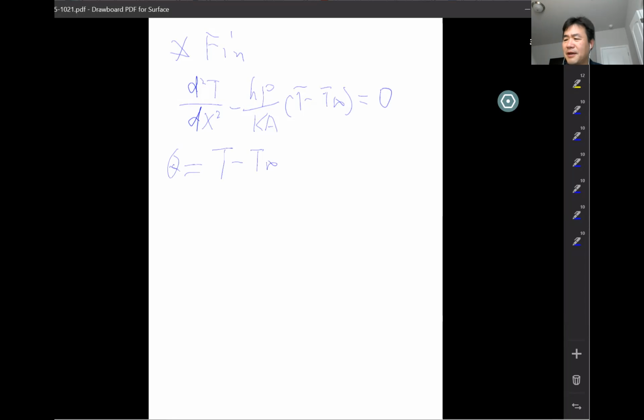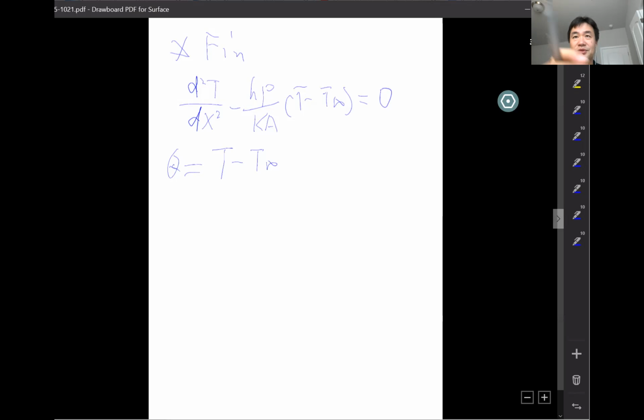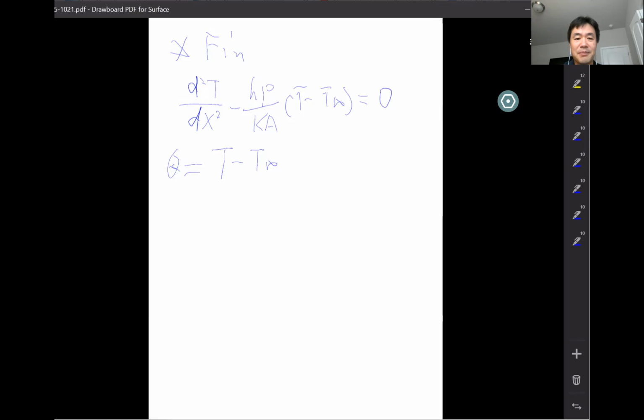Many of you were in my fluids class. We talked about pressure, and remember we used gauge pressure. Gauge pressure is also a relative pressure, referenced to atmospheric pressure. Everything above atmospheric pressure is positive, and if it's lower than atmospheric pressure, it will be negative gauge pressure. Same idea here with temperature: for any individual problem, we treat the ambient temperature as a reference temperature.